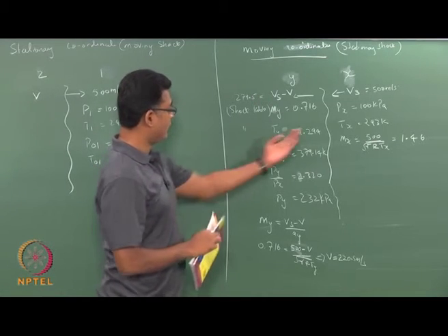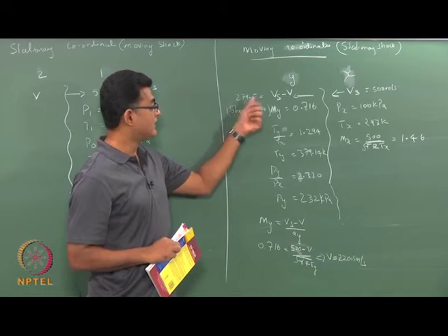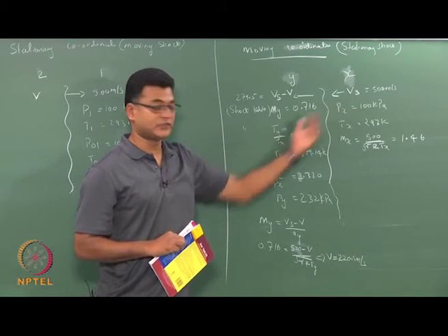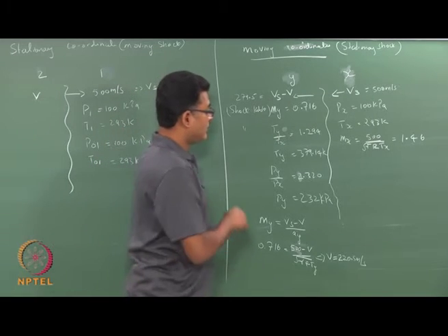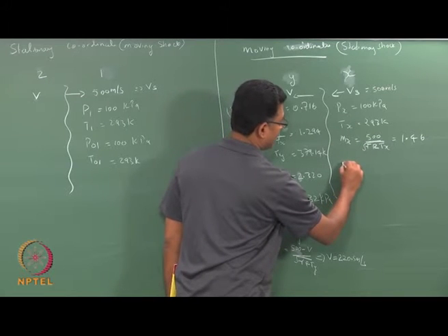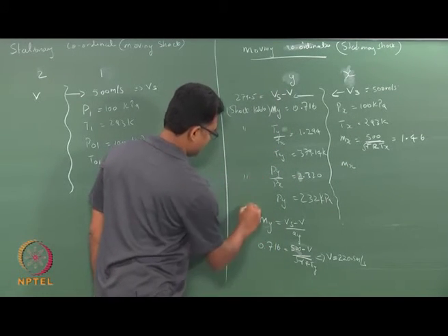Okay. So the fluid is receding with a velocity of 279.5 meters per second. If the fluid is coming and hitting the standing shock wave, I can also find my P0x from this, since I know my Mx. So all these are from shock tables.